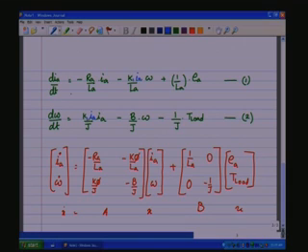So, because there is no state multiplication, I_A into omega, I_A into I_A, this is I_A square, this is a non-linear system. Therefore, we do not put it in the standard matrix form, we just leave it as a differential equation system. So, that would become a non-linear system, but still that would give you the entire dynamic model of the DC